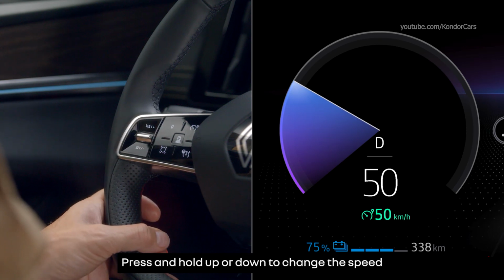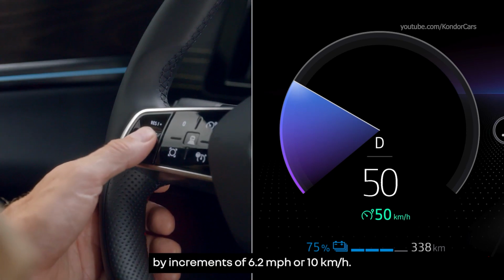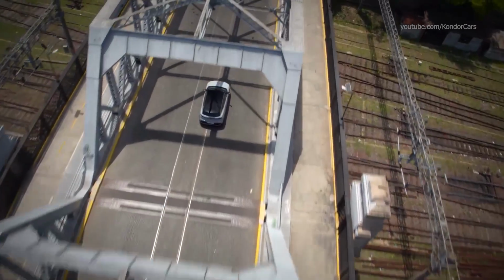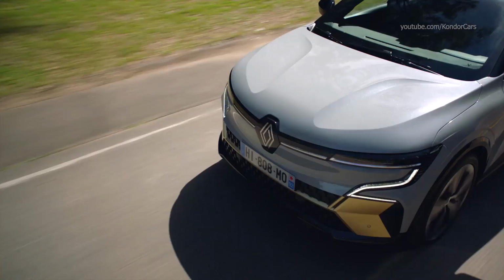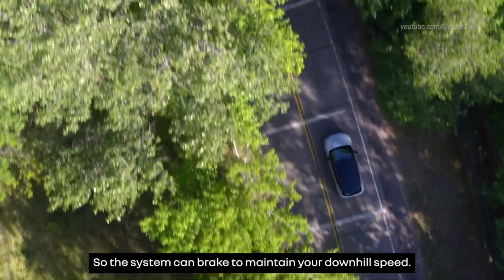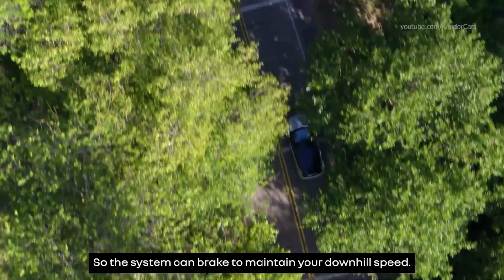Press and hold up or down to change the speed by increments of 6.2 miles per hour or 10 kilometers per hour. Don't forget that the speed limiter has a downhill braking feature, so the system can brake to maintain your downhill speed.